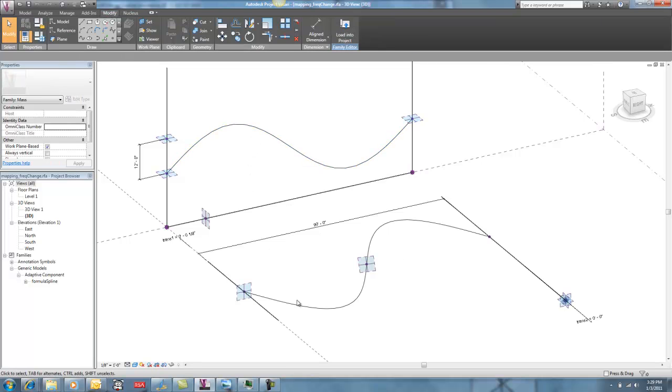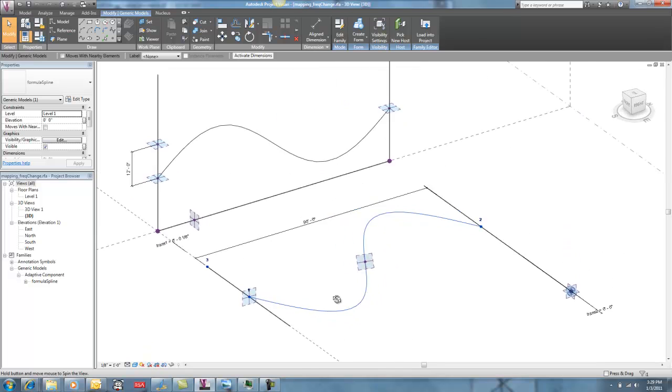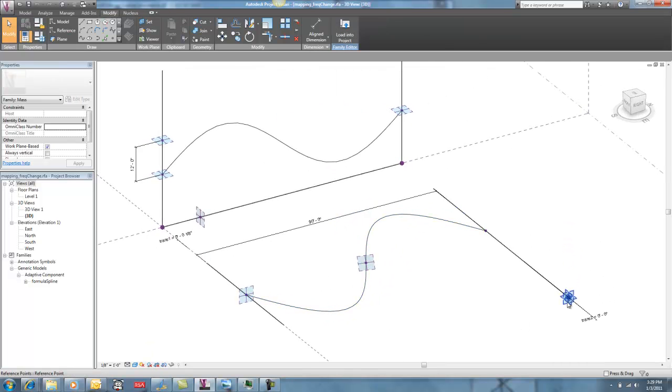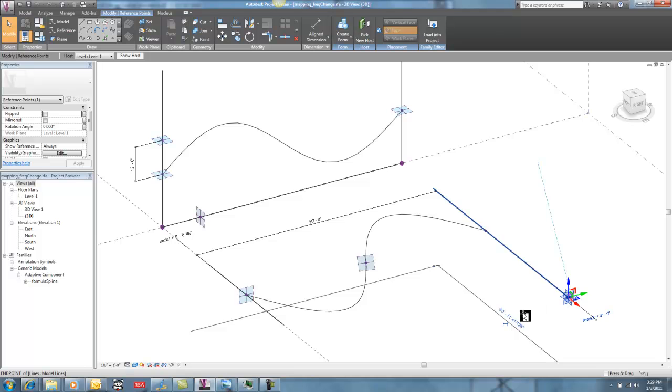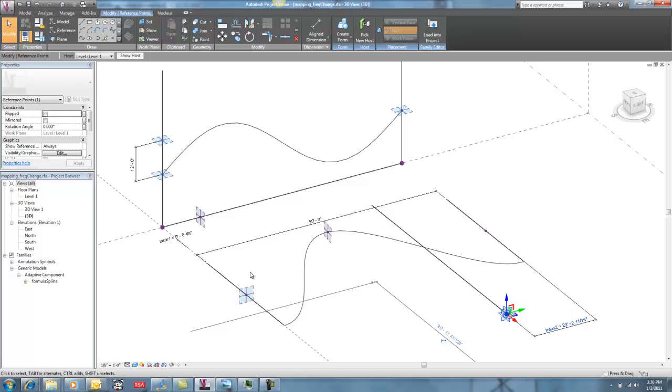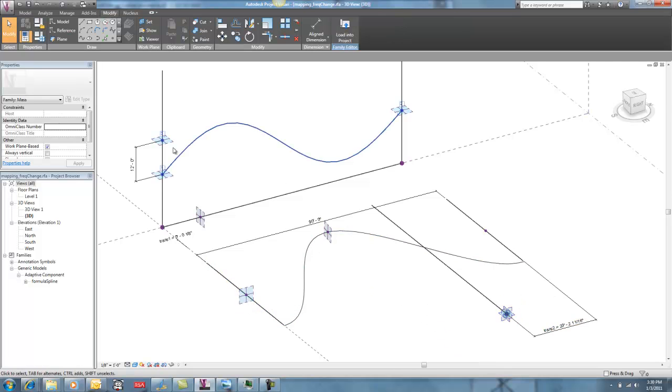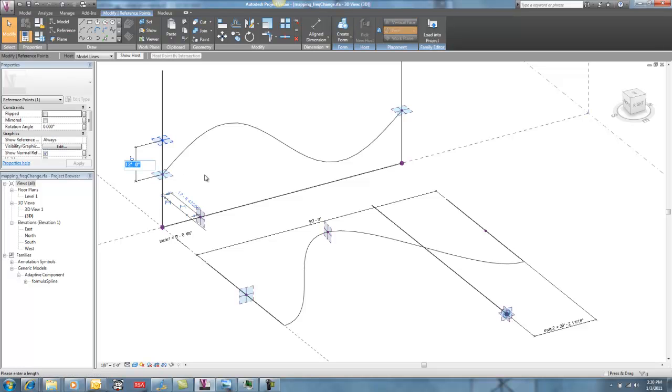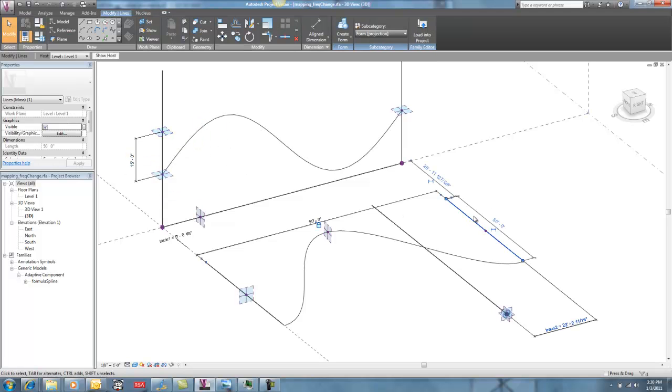These are both the same 3-point loaded adaptive component family, and you can do all sorts of things with this family, like you can move the waveform along. This is called the translation of the curve, so that the waveform starts at different points. You can change the amplitude of it through various means, and this is the same instance of the family. You can change what the range is, so you're going to see the same curve, but it's just going to continue farther or shorter depending on what I do with this.